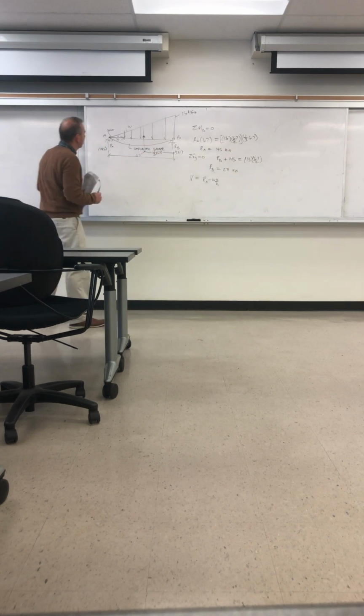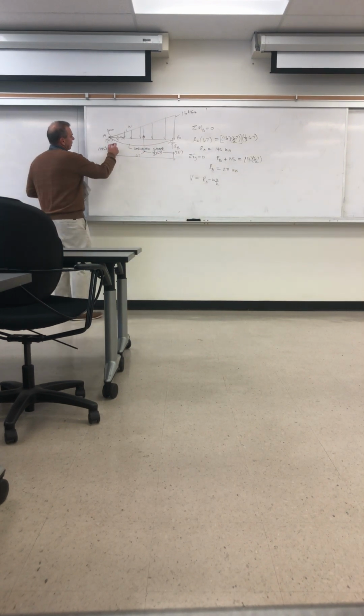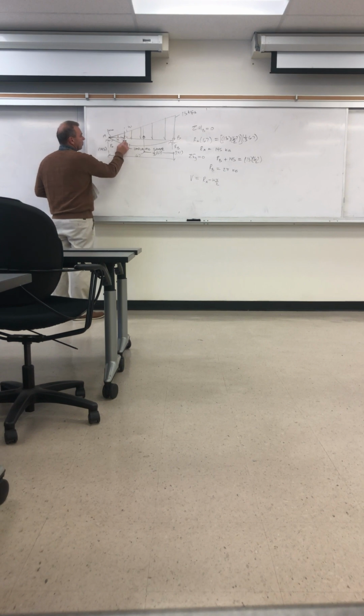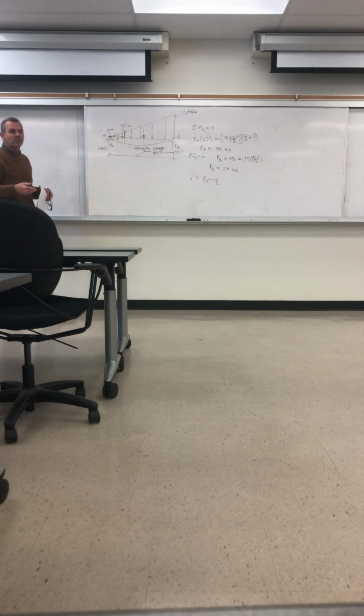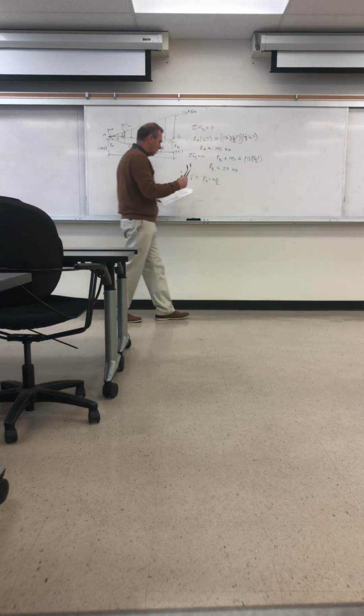W up to that point, right? So if I'm taking a cut here, the internal shear at that point is this force minus the total force that's occurred up to that point, and that's the W at that location. So the W times the x over 2 is the area of that triangle, which is the force down. So that would be the shear in that case.